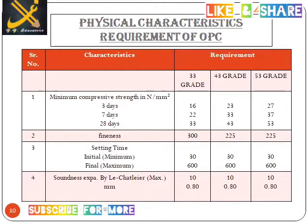Now see the physical characteristic requirements of OPC as per the IS standard codes. There are characteristics and requirements for 33 grade, 43 grade and 53 grade. The first characteristic is minimum compressive strength in Newton per mm square. Within 3 days, 33 grade cement achieves 16 Newton per mm square strength. In 7 days, 22 Newton per mm square, and in 28 days it becomes 33 Newton per mm square.